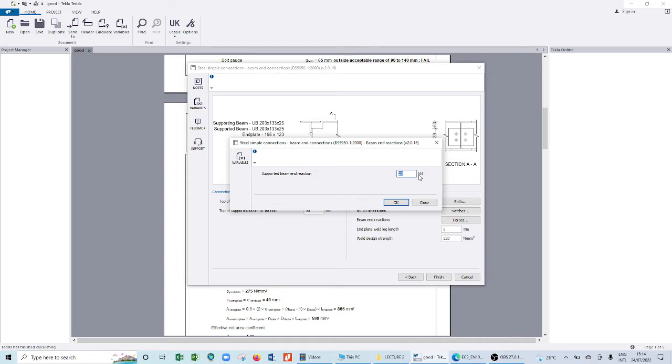my I-section, yeah? So meaning loading due to I-section. P equals, I have my 25 times the meter that I have. Yeah? 3. So we had it to be 3.12. But this is in kilogram. So I want to convert it to kilonewton. I multiply by gravity, times 9.81. So it is already in Newton. Now I want to convert it from Newton to kilonewton. So I divide it by... what do you get?